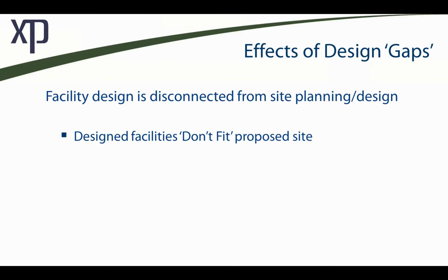So can that gravity drain to the stormwater connecting pipe? Can that drain from one facility to another? It's very, very difficult to understand if your swale will truly run and spill into, let's say, your rain garden, and then if that can connect into your downstream discharge point. Okay? Very, very easy to overlook.